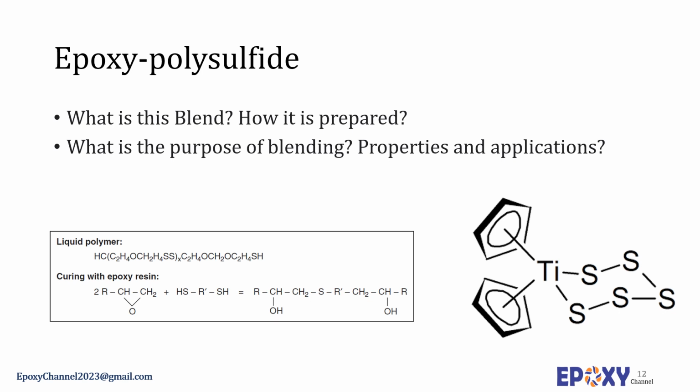Polysulfide compounds that are compatible with epoxy resins are liquid elastomers at room temperature. They often contain a high concentration of sulfur linkages that provides these products with their unique chemical properties. Polysulfides can be cured by themselves with an oxidizing agent as a catalyst. A sulfur odor is noticeable during processing, making ventilation important.